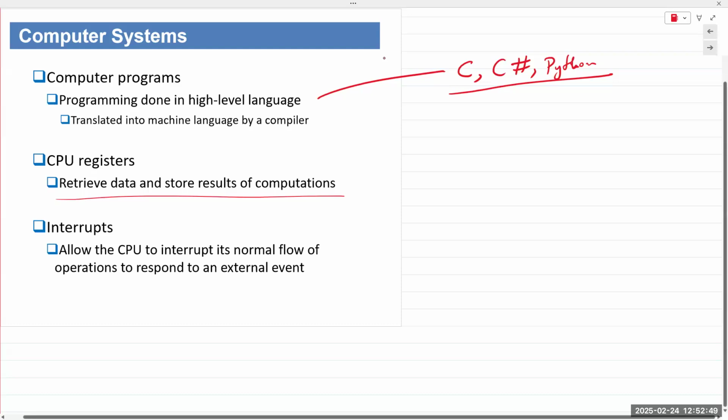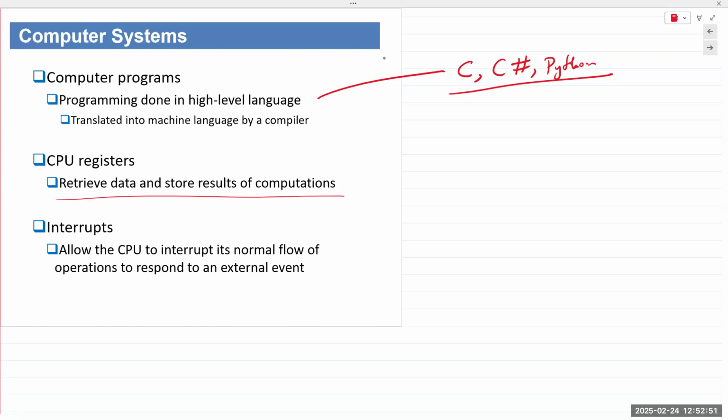So the CPU is interrupted from its work, and that's known as an interrupt. Interrupts are very common in higher level computing, meaning all the computing that we do nowadays, whereas polling is used in some embedded systems, inside your microwave, perhaps inside your washer, inside your dryer, inside any appliance that just needs minimum functions, not a full-scale computer. Okay, so that's interrupt. That allows the CPU to actually function.